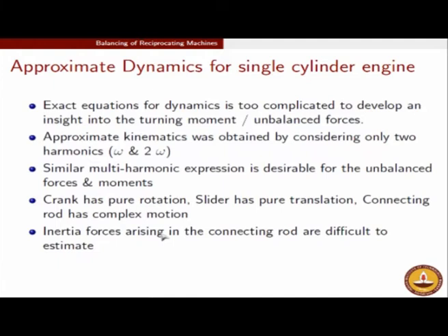Through a computer it is possible to determine, but again as I said, it is very difficult to get a formula out at this stage. So, the inertia forces will require us to find, let us say, the acceleration of the center of mass of the connecting rod. Unfortunately, that formula is not a very compact formula, not very simple to represent. So, this is where the difficulty lies in the exact dynamics, the complication lies in the kinematics of the connecting rod, which does not permit us to find how the acceleration of the center of mass is behaving with time. So, that is what we will try and mitigate in a simplified analysis.